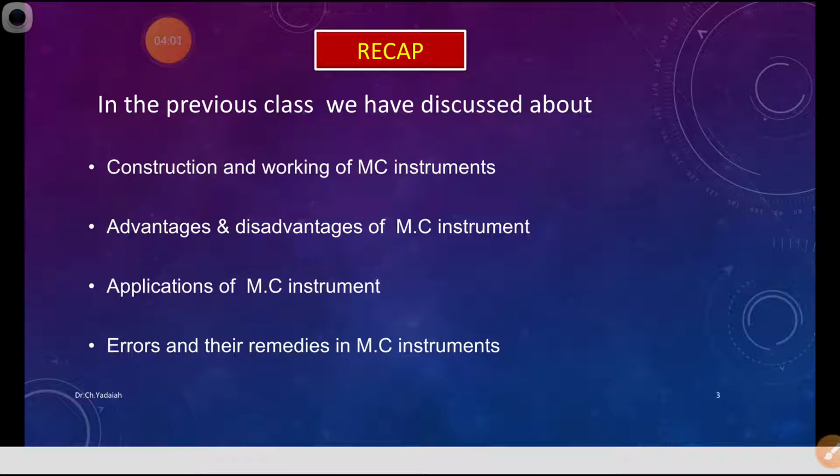Now, in your syllabus, we have seen the PMMC meter as a voltmeter and as an ammeter, how to connect them in real-time circuits, what the unknown shunt resistance and multiplier resistance, that is the series resistance, are, how to measure that value, and how these instruments can measure the value with the help of shunts and multipliers.